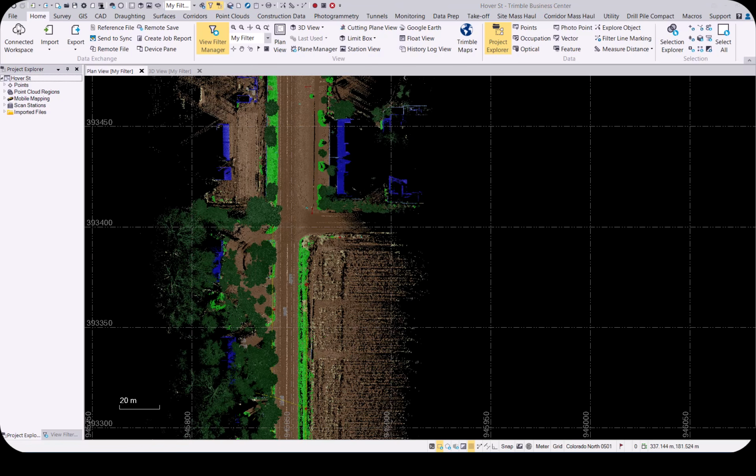Next up, let's have a look at photogrammetry. Nothing specific to show you. The most important thing about the photogrammetry module is we still can import any third-party drone sensor that you can use. We've also enhanced the handling of unorthodox flight plans and extreme scale changes, so that would be much better in this release. And then in the processing of digital surface models, you will see a 20% improvement in the time it takes to do true ortho generation, and disk space requirements have been significantly reduced by 50% when you do processing.